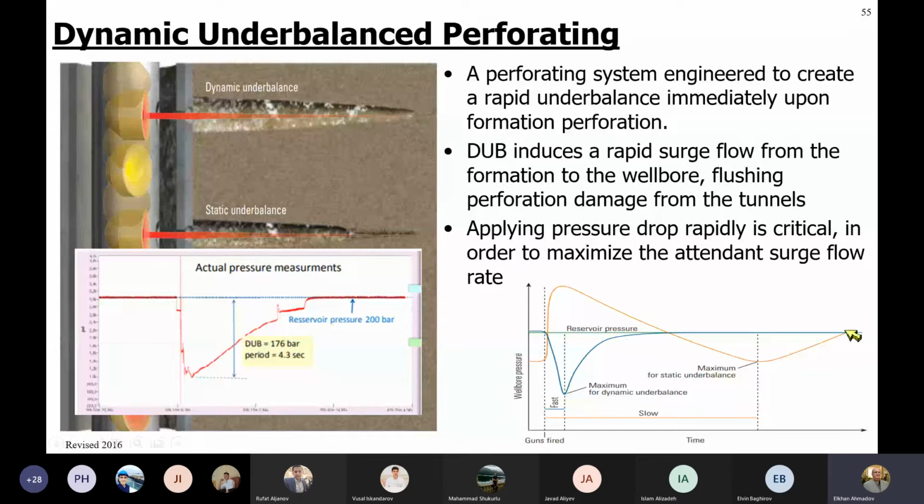In this case, the balance between the wellbore and reservoir is achieved. Therefore, the bottom hole pressure is reaching the reservoir pressure and it's balancing. This is assuming that we are not producing the well, but we are perforating it under balance conditions, just to get some flow from the reservoir to clean the perforations.